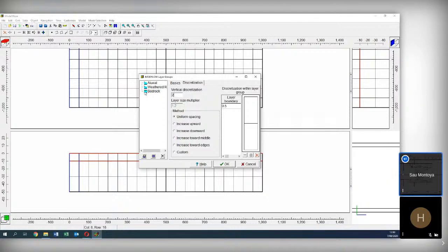If you are doing regional modeling, maybe 5 layers are enough, because you are also restricted by the number of cells. It is advisable to work with 500,000 cells at maximum, maybe 1 million cells, but please do not go over 2 million, even with Model Muse, because the software will crash. It will take a long time to review the results and so on.